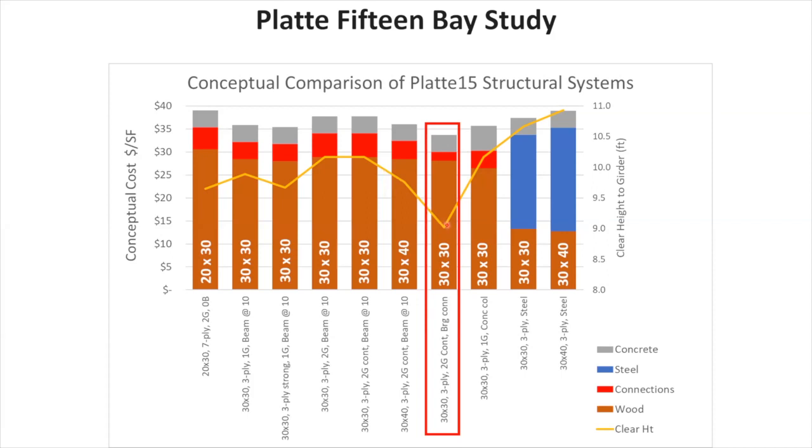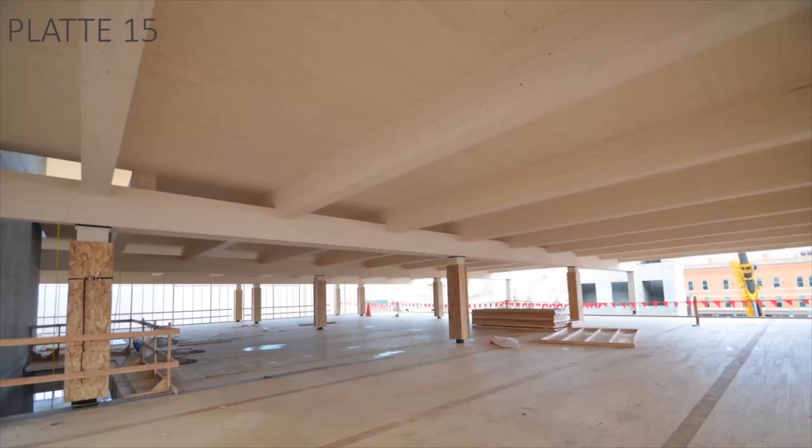You can see here of a dropped ceiling height. This isn't that accurate, actually. It ended up being exactly 9 feet, or 9 feet 0 1/4. So this is what that system looked like in the end, right? You can see our dropped girder, dropped it about 16 inches below the bottom of the CLT so that we could sit the beams on top and make that connection simple.